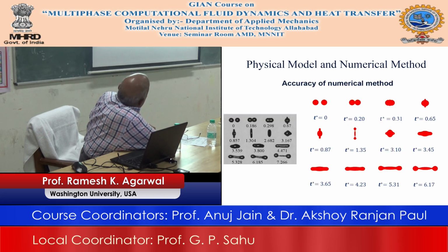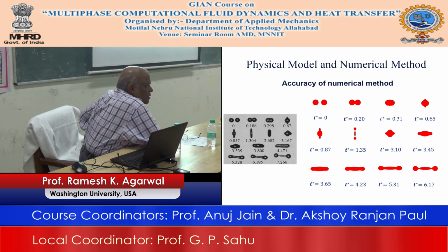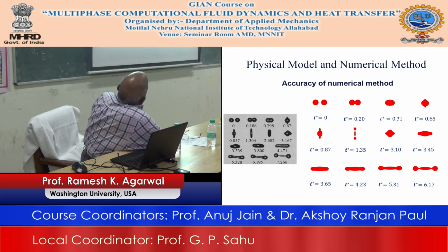So anyway, there is a paper here, and this paper has solutions that can be trusted. It has the regimes of coalescence and separation in droplet collision, and C.K. Law has done an enormous amount of work. I don't know whether anybody has heard of him. In droplet combustion, he is an authority, and this is a paper by him that we have used, published in the Journal of Fluid Mechanics quite a while ago, to validate. Reynolds number is 296, Weber number is 61.